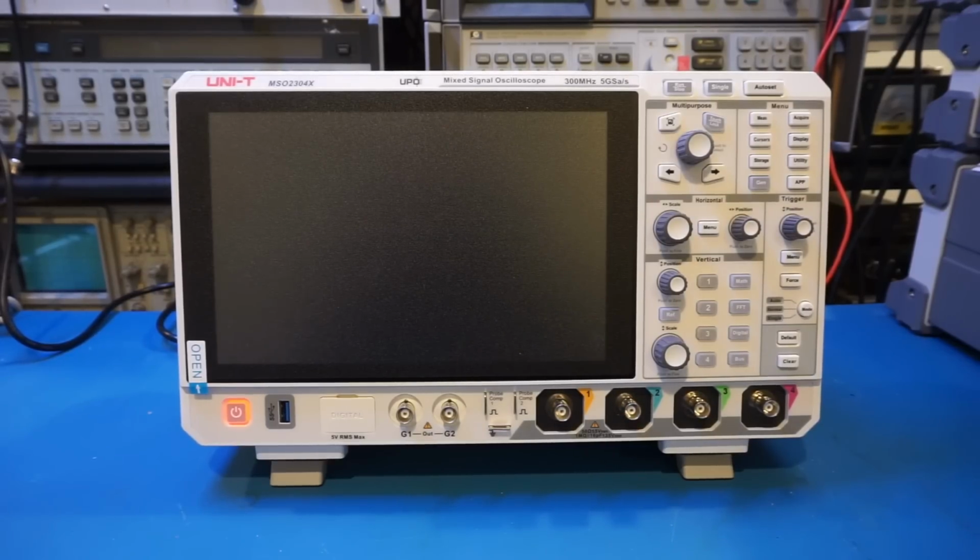Also, it has a built-in 2-channel 250 megasamples per second 16-bit arbitrary waveform generator, which supports output frequencies up to 50 MHz. It can also do power analysis, which is useful for people working with switching power supplies. Of course, the MSO2000X also has built-in high-resolution digital voltmeter and hardware frequency counter, which to be honest most digital oscilloscopes do nowadays, and I probably wouldn't characterize these as separate features. But nevertheless, the UNI-T scope is capable of doing this as well.